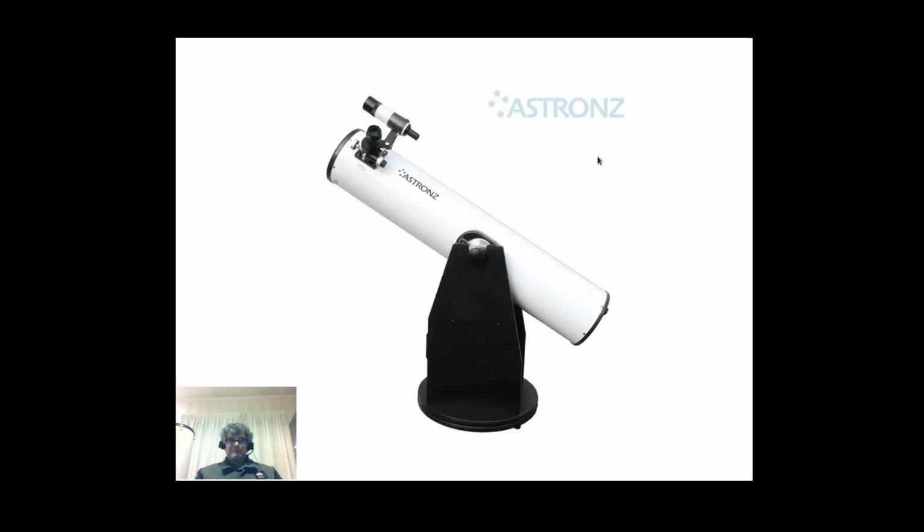So this is the modern version of the Dobsonian, I guess you could say. You notice the telescope sits on what you could call a rocker box, and the rocker box sits on two discs, and between the two discs at the bottom there's a bearing which allows the telescope and the rocker box part of the mount to rotate in azimuth. So normally the bearing will have an adjustment, and on this one there's actually a knob in the middle which you can't see here between the two side pieces of the rocker box at the bottom, where you can tighten or loosen the pressure on the bearing.